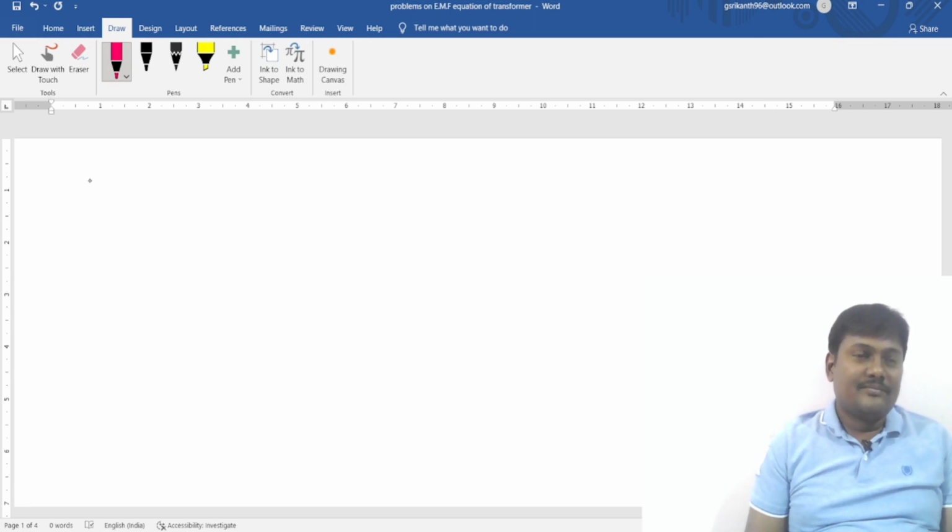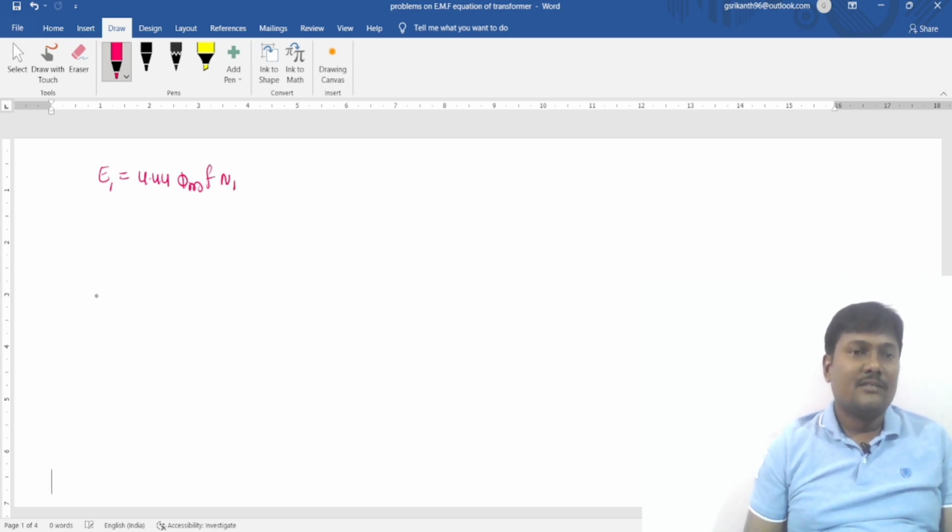In this lecture, I will solve some of the most important problems on the EMF equation of a single phase transformer. In the previous session, I derived the EMF equation of a single phase transformer: E1 is equal to 4.44 into Φm into f into N1. This is called the primary induced EMF. The secondary induced EMF is 4.44 into Φm into f into N2. This Φm is called the maximum value of flux.